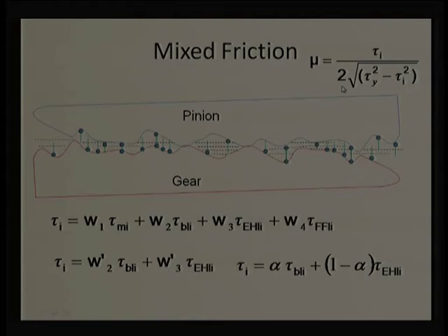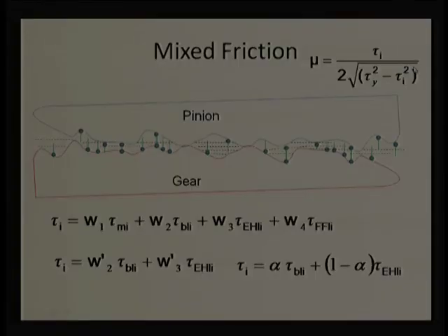But if we want to compare different material pairs, different hardnesses, different lubricants, or different profiles, yes, this kind of relation can be used. So, this is a relative parameter. Obviously, it can be used as a comparator, but cannot be treated as an absolute value.